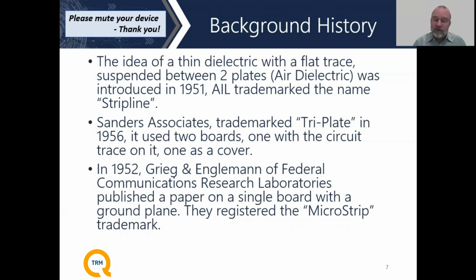In 1956, Sanders Associates trademarked the name triplate, and that basically used two PCBs with one circuit board in the middle with the trace on it as the cover. Now, this is what we traditionally would consider a strip line circuit as how we would build it today. So this was only trademarked in 1956, only 4 years prior to Wilkinson's development of the Wilkinson Power Divider.